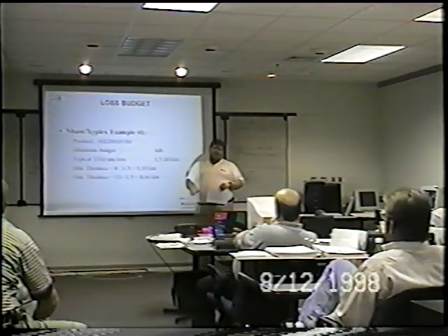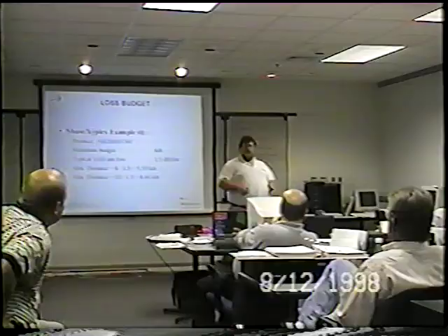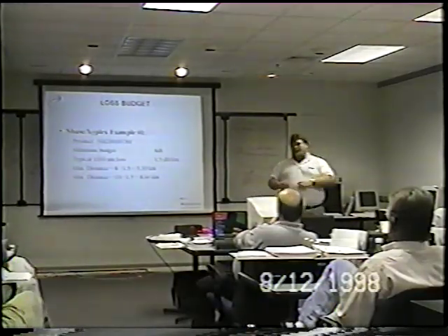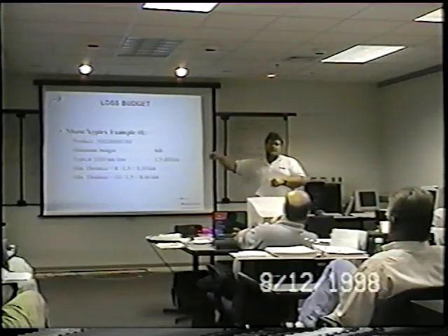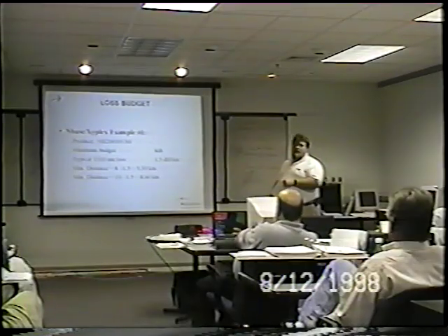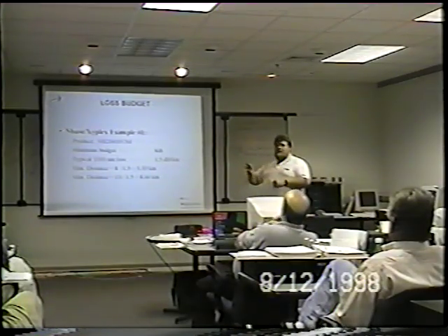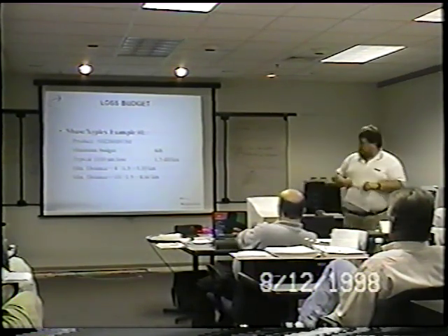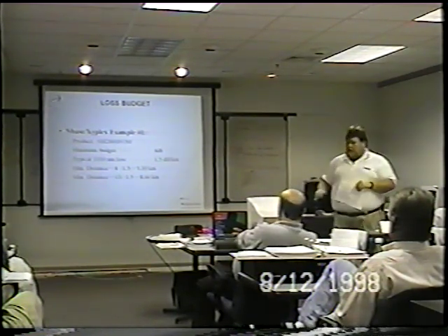If it's a private, fairly new installation, you're not doing CO hops, it's private premise, patch panel, backbone fiber, patch panel, premise, then you don't typically have as many interruptions in the fiber as you normally would. That allows you to maybe dip into that 5 dB of budget and pick up a little extra distance as well. So those are some of the typical distances you'll see on the 2001.